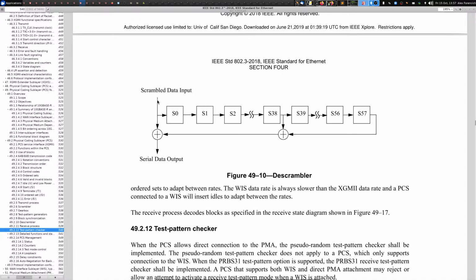If you get one bit error, then 39 bits later you get another bit error, and 58 bits later you get another. This is not good when you're using forward error correction, because for every bit error you get over the wire, you now have to correct 3 bit flips. So different techniques are used when you're using FEC.